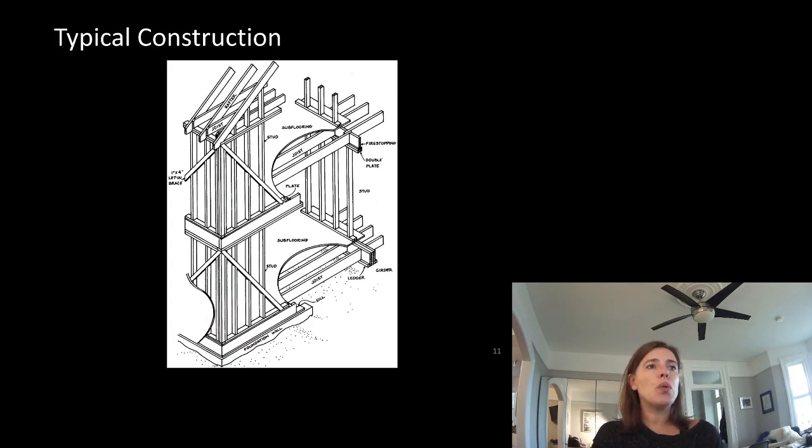This isn't anything for you to study. I just wanted to show you a cut-up opening of typical wood construction. You can see our joists at 16 inches on center. There's our wood floor. You can see studs at 16 inches on center with some sort of plywood framing on it. Don't worry about the let-in brace. We don't do that very often anymore, although it does still show up, and there is a slide in this where it shows one of those.